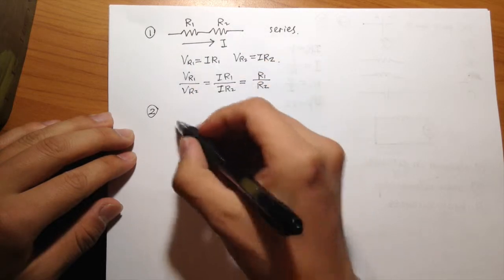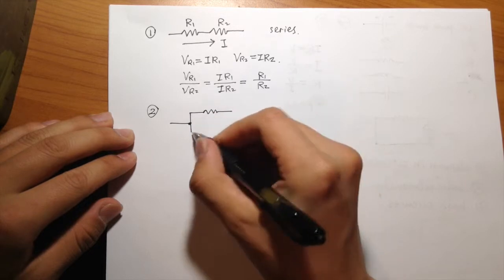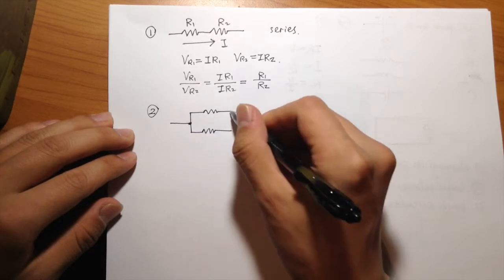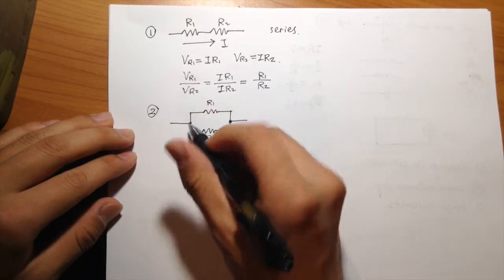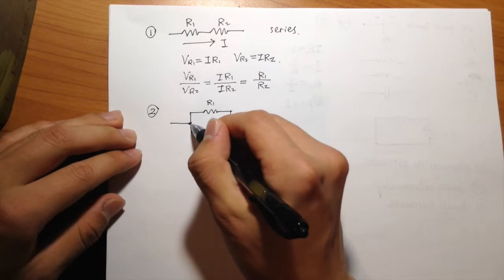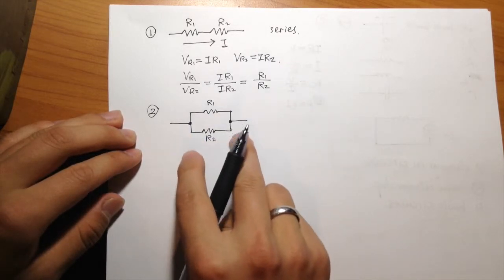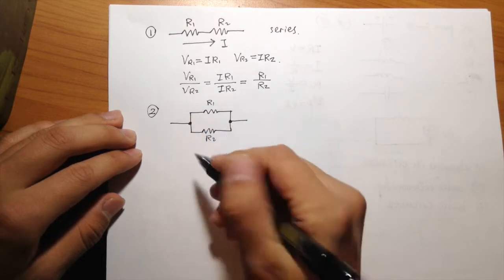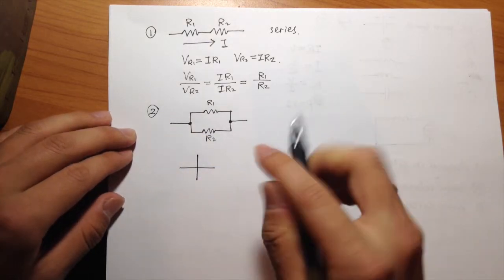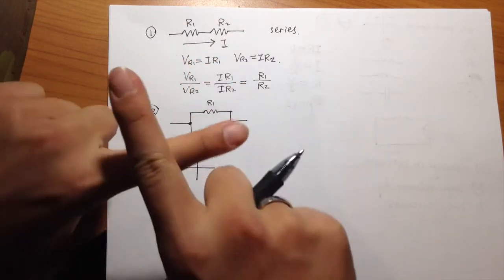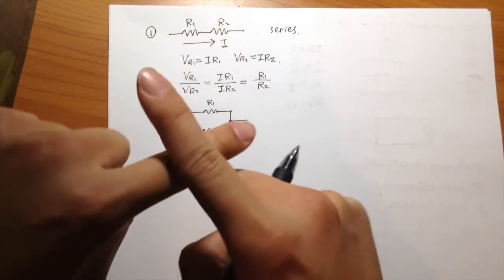And when you connect two resistors in a different way, that is in parallel, then we have a current divider. Notice that I draw two dark dots where the wires are connected. These are used to indicate that the wires are actually connected. If I don't have the dots, then the wires would not be connected. They would go over each other so that there's no current interference.